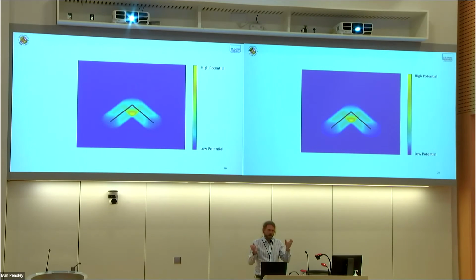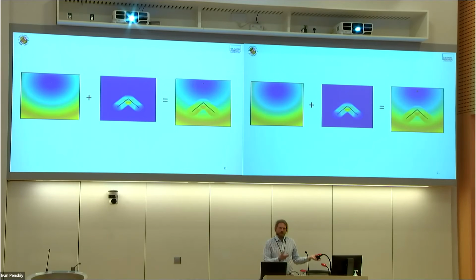You can also model the obstacle using this potential field. So you're pushed away from the obstacle. It'd be like having a negative robot and a negative obstacle. They're going to repel each other. But when we sum these two fields, obviously we can get a local minimum, which means that we can get trapped without actually getting to the goal. And this is the Achilles heel of potential field methods, widely known. If you do take the time to do a literature search when you reinvent the wheel here, then you will find out that there is this problem.